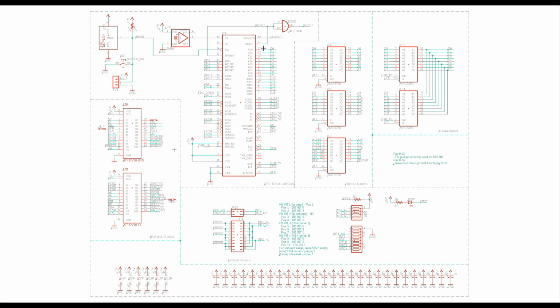Now, there is no BLE, but what it actually does for bus low enable is that BLE is shared with A0. So when A0 is set, it is asking for the low byte on data lines D0 through D7. So that gets us our 16-bit data bus and our 20-bit address bus, our state bits, and our high and low enables. Now, when we talk to I/O devices, we want to talk to those 8 bits at a time.